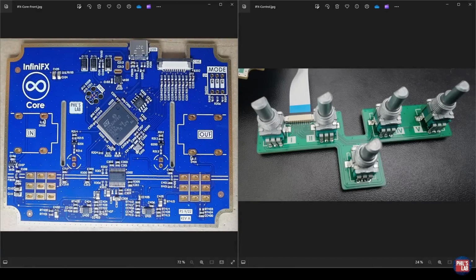In this video, I'd like to go through the steps required to configure an STM32H7 microcontroller to use its built-in analog to digital converters, or ADCs for short. Several of these ADC channels are triggered by a conversion timer running at a fixed sampling rate, so we're going to use an internal hardware timer from the STM32 to trigger the conversions, and we would like to offload the transfer of our measurements from the ADCs to the required memory locations via the use of DMA, so that it can effectively run in the background. Using ADCs is very common in many embedded systems.